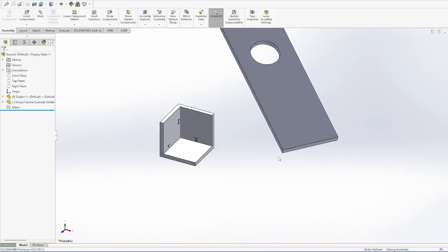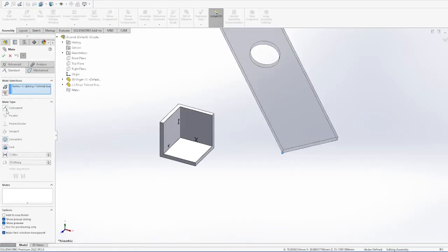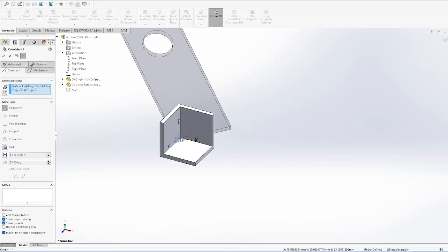I'm actually going to tab over to SolidWorks real quick because I want to show you guys how the fixturing that we're about to do works. So in general, when we are looking at the XYZ plane, it's a bad practice to fix one end, and I'll show you why that is at the end. Instead, we want to do realistic boundary conditions, and so I wanted to animate that for you, and this is just the best way I came up with.